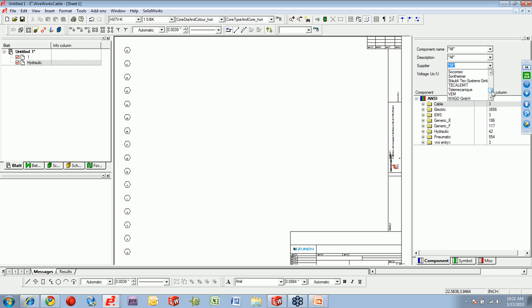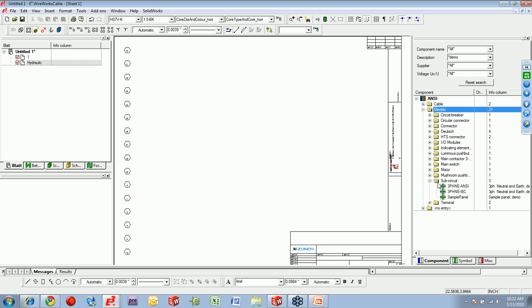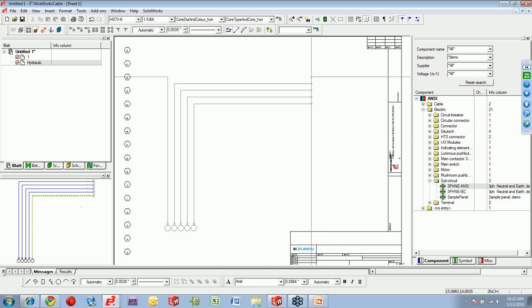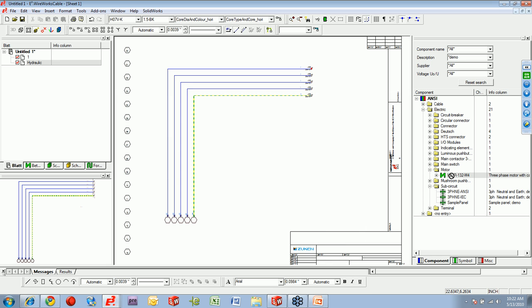So you can go down to Siemens, for instance. You can see that there's literally 1,000 components from Siemens from multiple different categories. And let's filter that list just a little bit more. Let's focus in on just a few demo examples for today. I'm a big fan of working with subcircuits. If you do have wiring that is common between many different parts of your design that you use over and over again, it's a great example, just feeding power into your design. You can just drag and drop a subcircuit in, and then you can continue designing without doing all that stuff from scratch.